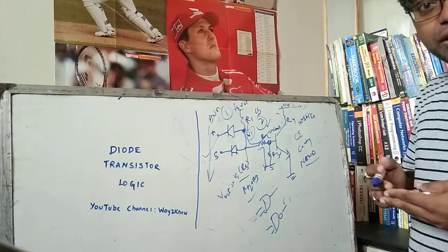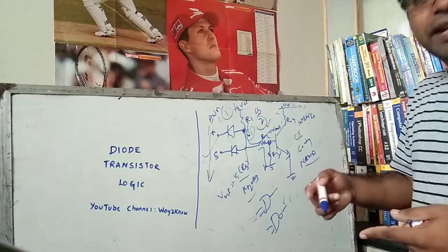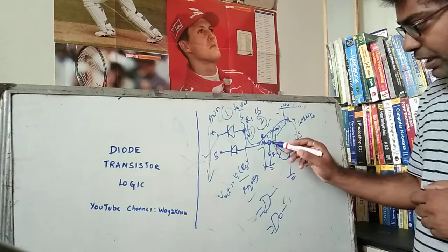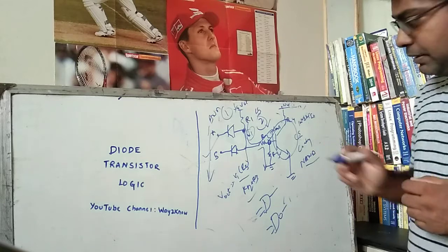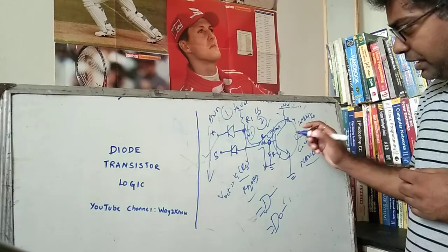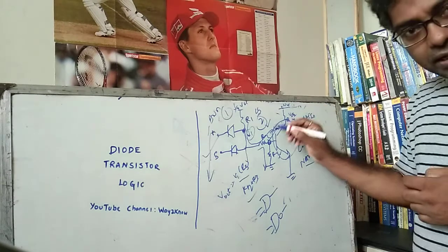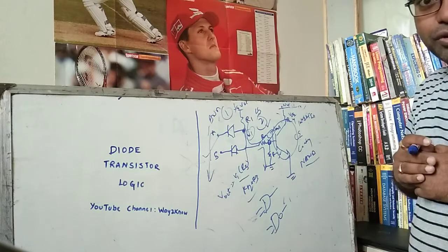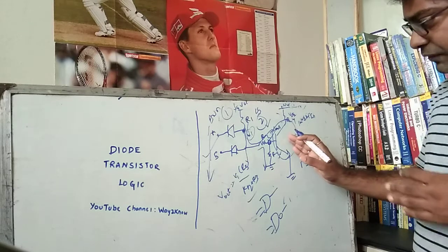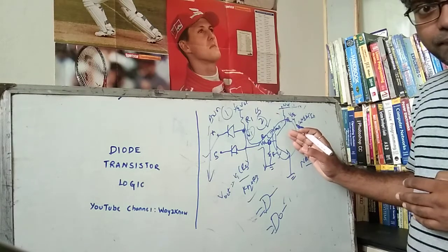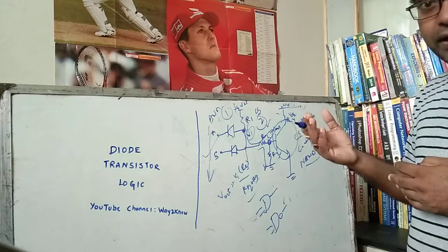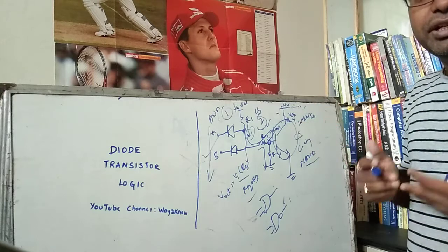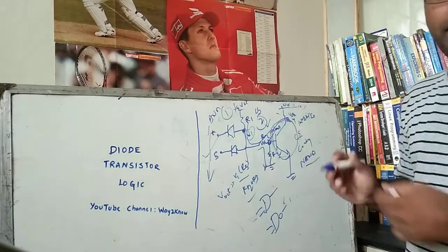Now there are ways to address this. One of the major reasons why this has a high propagation delay is this particular transistor you see here. When you drive this voltage on the base, the collector current gets driven, and this drives this particular transistor into saturation. It turns on and goes into the saturation state. So to bring it into an off condition, the opposite of on, you need some time for this to get cut off from the on condition.